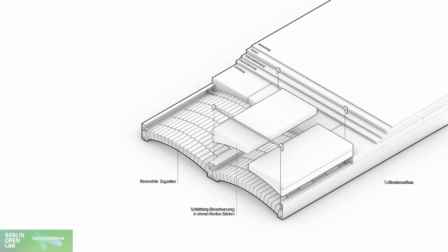As it is vaulted, the structure is purely compression loaded, as opposed to a reinforced structure where you have tension and compression in the system. In this case, we can separate these two things. We can put tension anchors into the system that you can screw out in the end, and you have the compression-loaded masonry, which you can take out in the end.